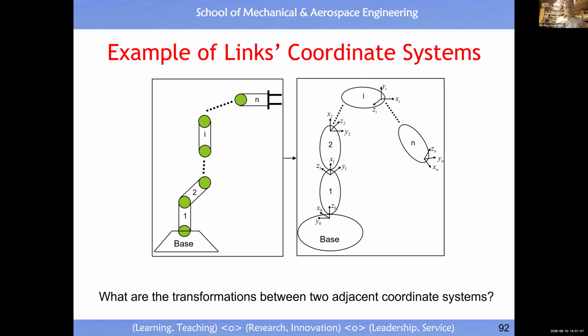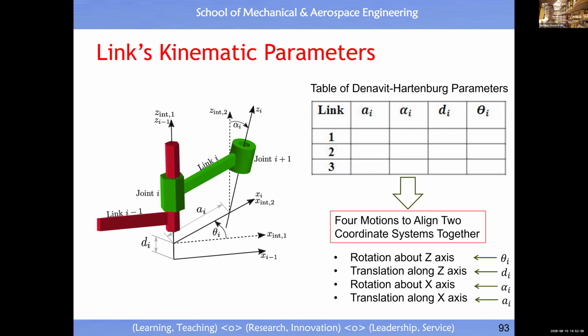So it's quite simple, but quite important. Try not to confuse yourself, okay? Follow the convention, then you will not make a mistake, right? Okay. Then on top of the assignment of a coordinate system and the kinematic parameter of link length, what are the other parameters? Actually, in total, there are 4 kinematic parameters, not just one, the link length, right? So this table helps you to know these 4. We put them together and call them the DH parameters.